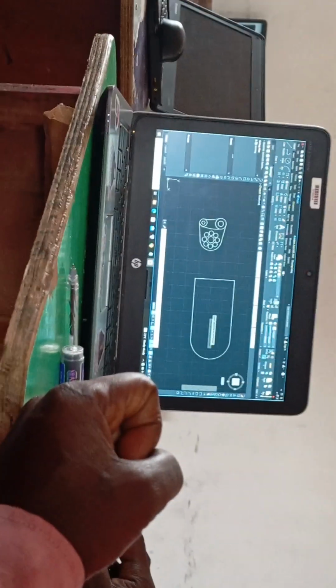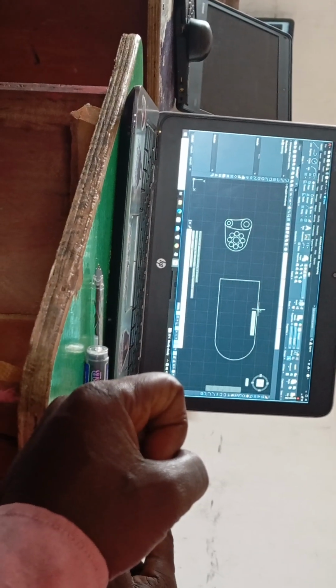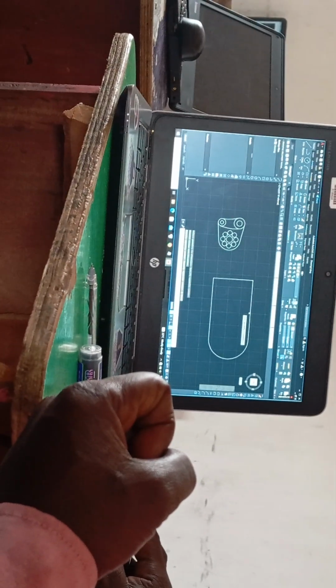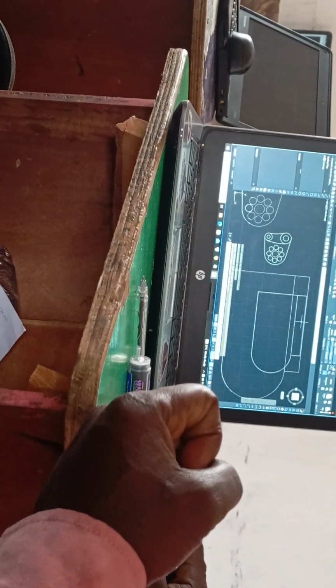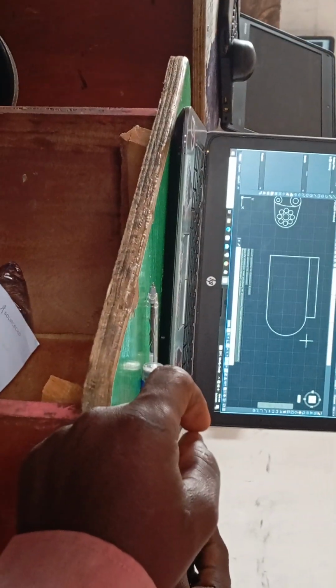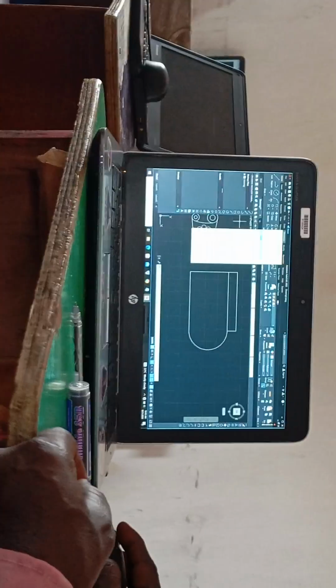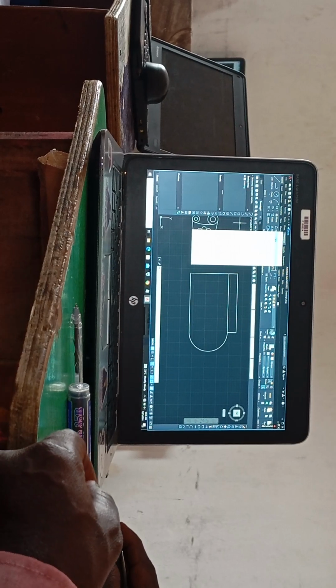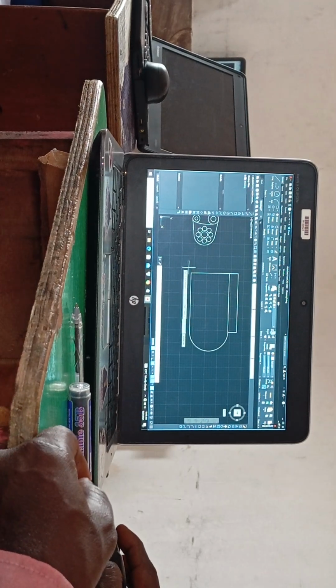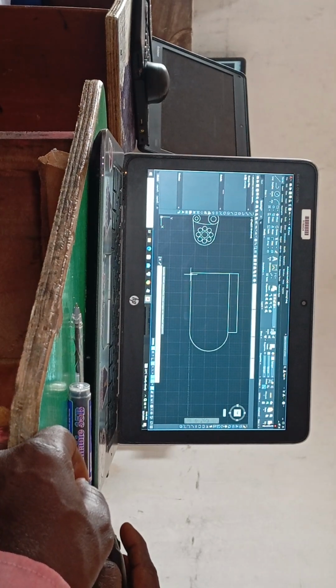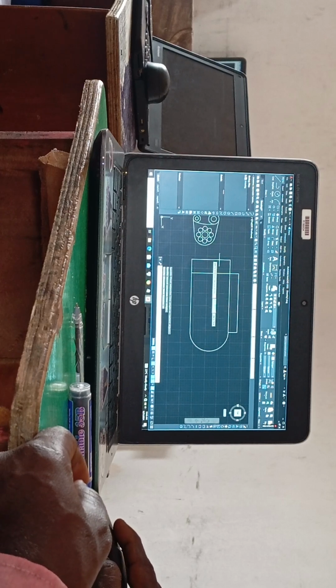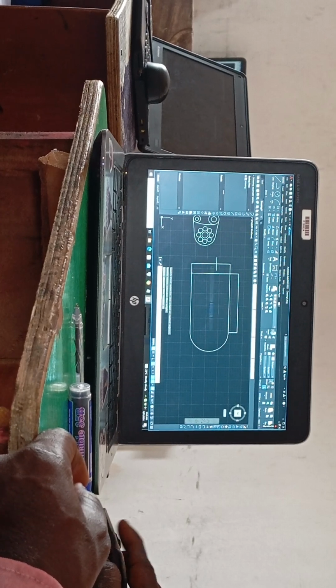Dimension. You click the object to dimension. You right click and drag it out. We're not seeing the dimension. Yes, correct. We need to go in there and set it. Then let's go to, after that you have align. To use align dimension, you click your first point and second point. You drag it out, click your position to position your text.